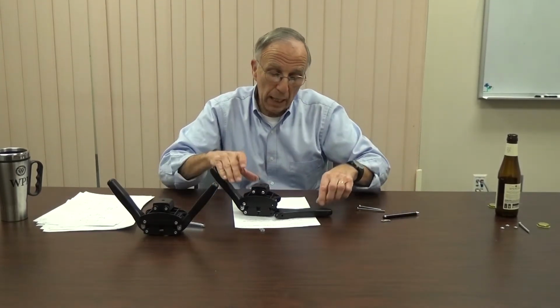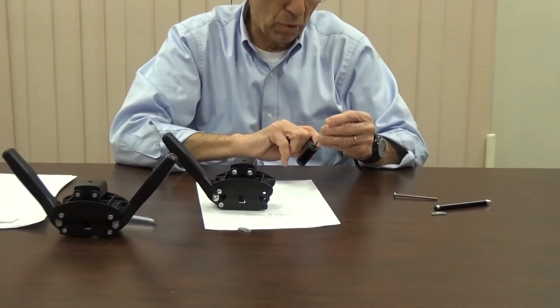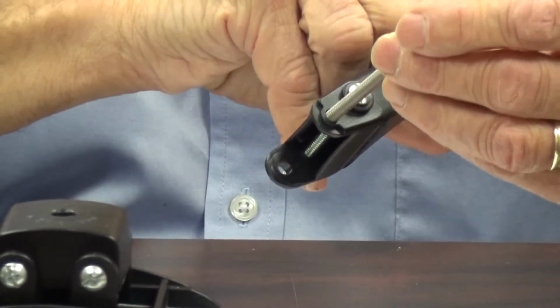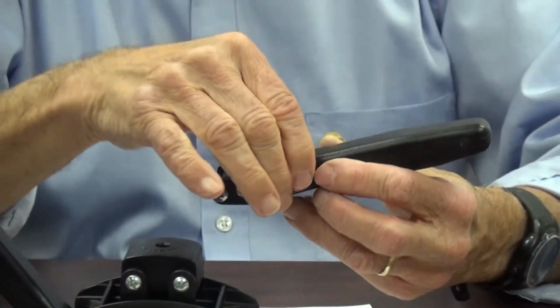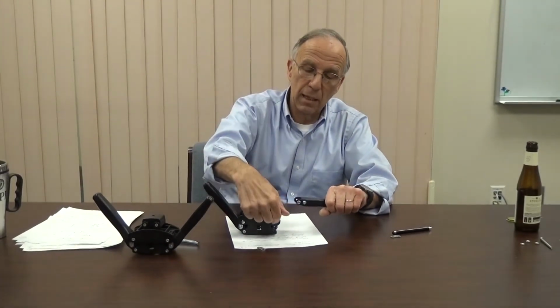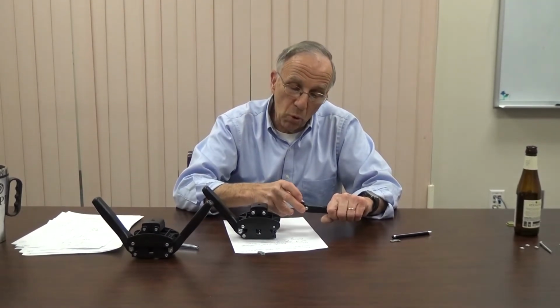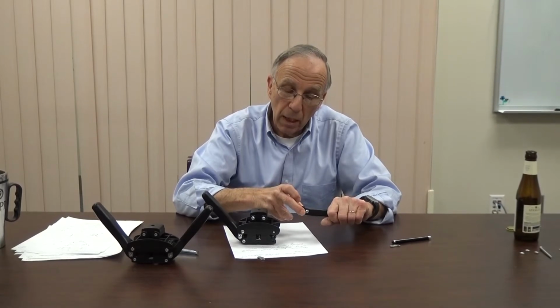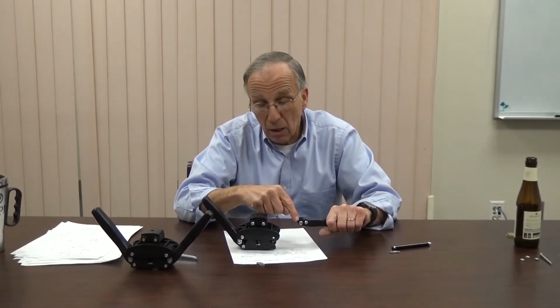The next member we'll look at is the handle. Of course, the handle has two pivot points. We'll drop the nuts in between here. And so we can have a variety of stresses here depending on how it's loaded. Now, it's most heavily loaded when it's essentially in this position and the links are connected up to here, so they're on a slant plane. So we could have a case where we pull out of the material, and well, let's go back to the pin. The pin can fail in shear because the pin is basically in shear where it's held. Of course, these are steel bolts, so it's unlikely that's going to occur.